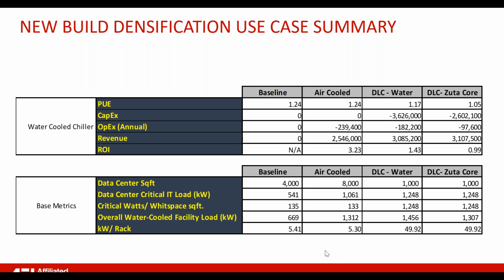Having said that, it's very typical that the rest of the components on the board do not require that level of ambient temperature as the CPUs and GPUs require, and therefore, if you account for higher temperature there, the fan power is reduced to about 5 to 10% of what it would be without the direct-on-chip evaporators. And that still requires some level of air cooling as well.